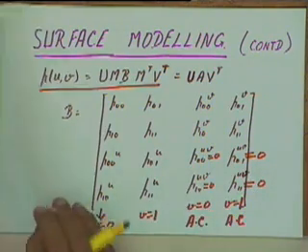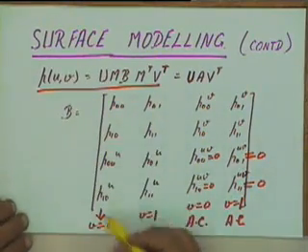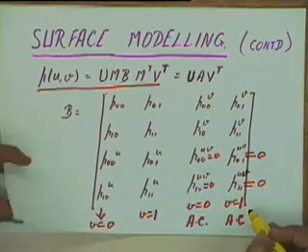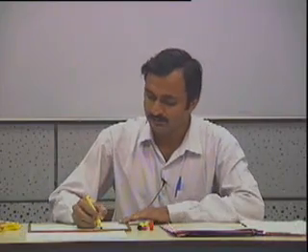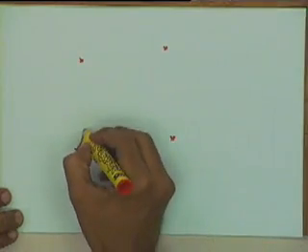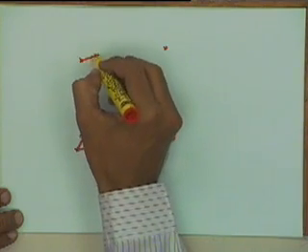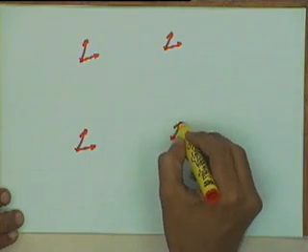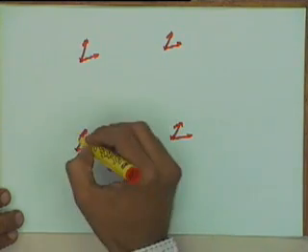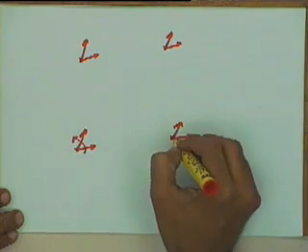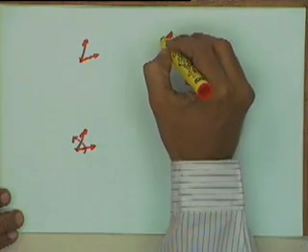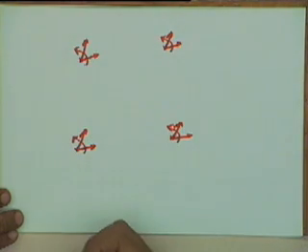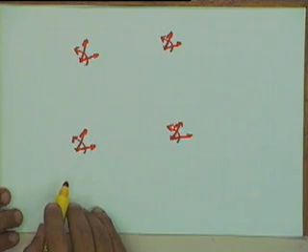Now, what we will see is that instead of inputting a surface through these 16 vectors, these 16 vectors are the 4 corner points, tangent vectors at the 4 corner points, and the twist vectors, which let us say I represent by 4 curved arrows like this. So these are the 16 inputs we are giving right now.